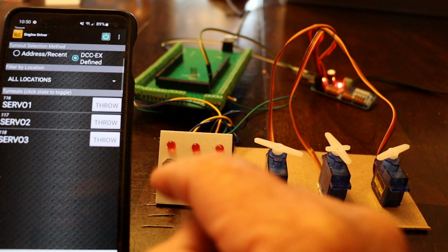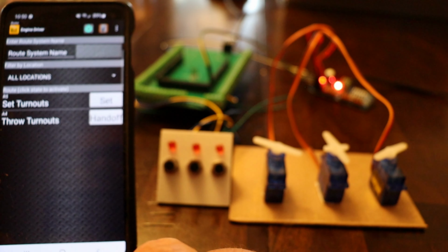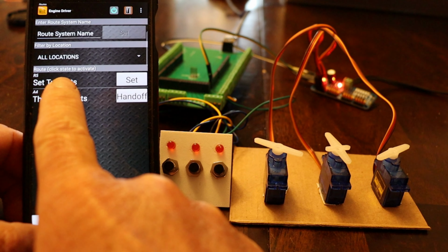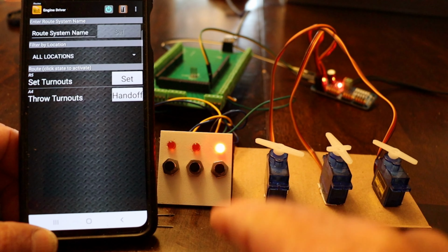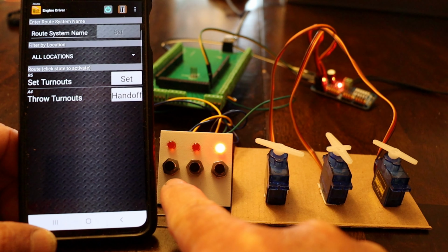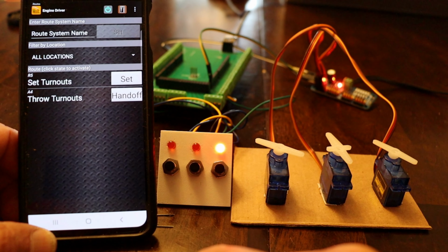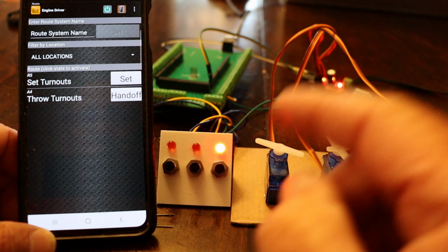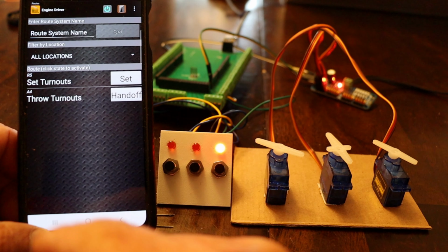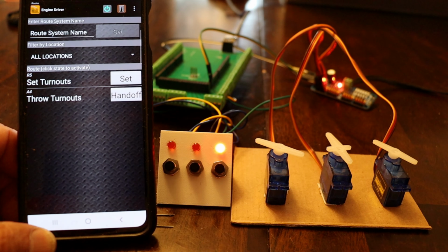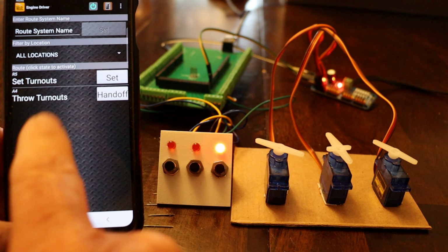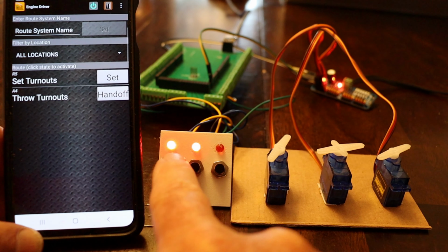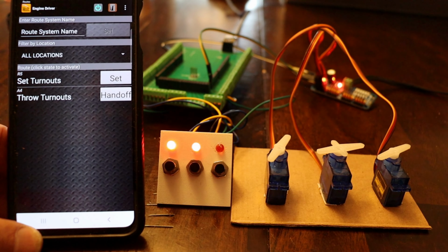Now, I also mentioned in the earlier section, I was talking about routes and automations. So under this routes button here, the first thing we've got is this R5, the R is for routes, set the turnouts. And if you remember that, when we set it, it was to throw the first 2 turnouts and close the 3rd one. Maybe you've got a predefined route. You've gone from the main line into a switching yard, and that's how you would get to that yard. You can predefine it. You can give it names. I used set turnouts when we were identifying that. But when you operate it, okay, you see it moved all 3 servos to the position they were supposed to go to, and again updated the LEDs.